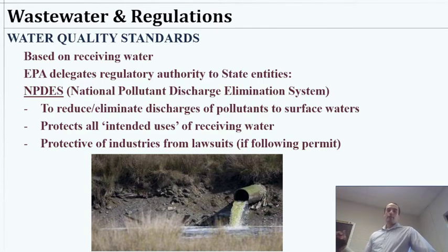In that type of system, if you end up discharging a lot of particulate matter that ends up floating through the septic system and making its way into those pipes, you could clog them. The same issue might apply to a groundwater discharge. You don't want to clog up the soil too badly. So I assume that a groundwater discharge has some higher need of particulate matter control.